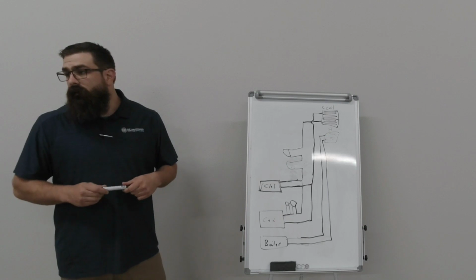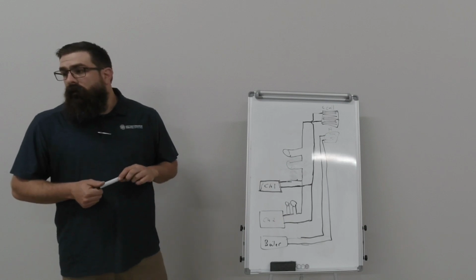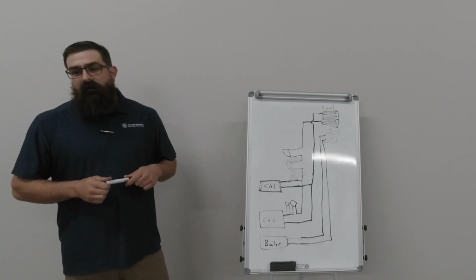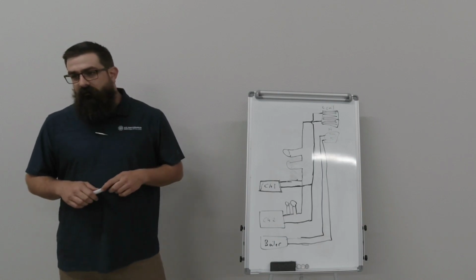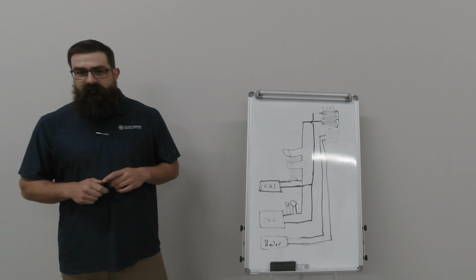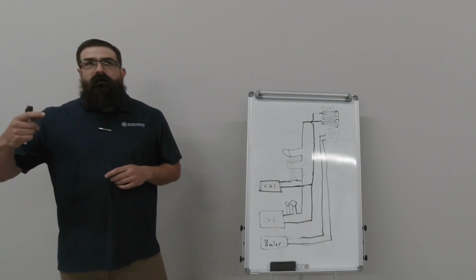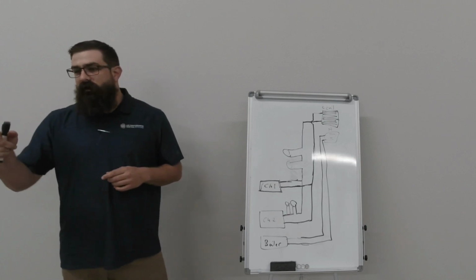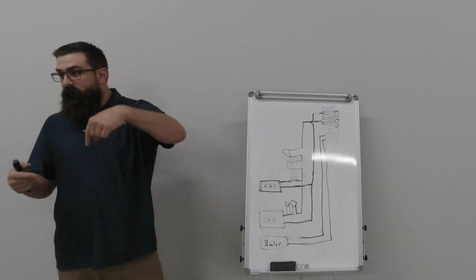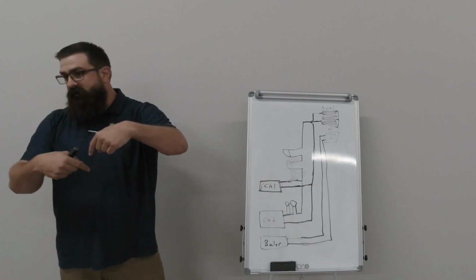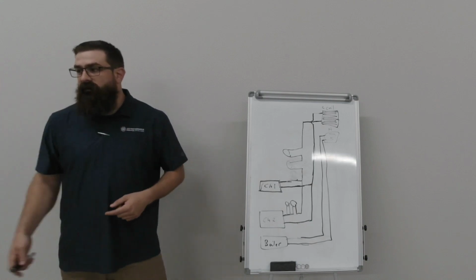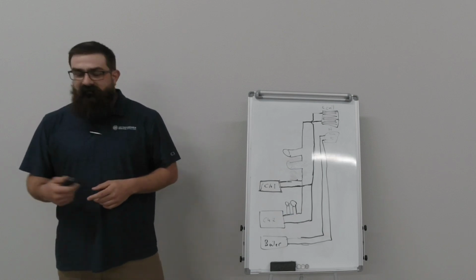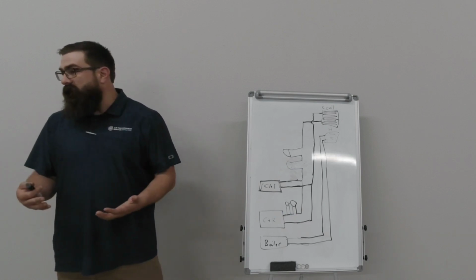Are the pumps normally on the entering or leaving side of a chiller? So typically they are on a chiller. Where does it matter? It does. Most of them are pushing through a chiller, so it would be on the return side of the building, pushing into the chiller and then out to the building. Pumping it in. Yeah.